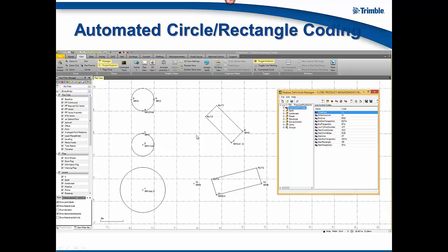With the rectangles, in this example, you can also specify a manhole, and you can say start rectangle and -4 as the offset. In the case you don't know the width parameter in advance, you can simply collect 3 points. TBC is going to use the third point to define the width of the rectangle.